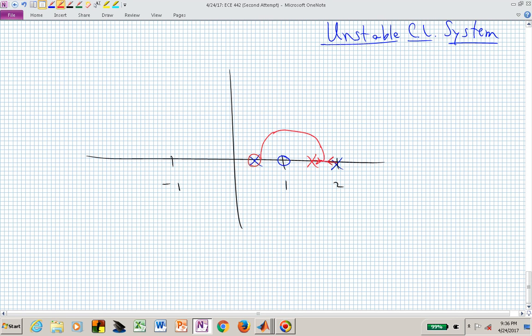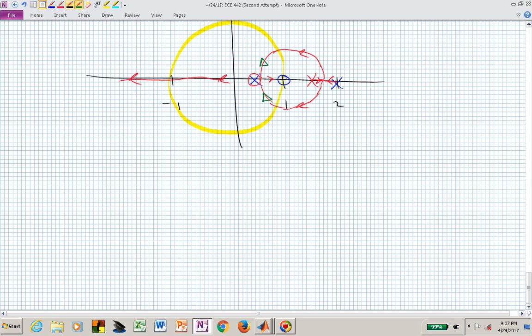We now are coming in here, and that's obviously not drawn accurately, but these two would now be giving rise to a potentially stable closed loop system for the appropriate choice of gain K. So in this case, we actually introduced a controller that now had a pole factor of z minus 3/2.